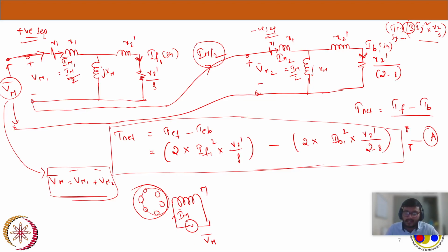Now let's compare this circuit and also the equivalent circuit. Now we have VM, okay, VM is okay. We have given the entire supply as VM, and then it should make the current flow as IM. But what is disturbing us here? The series current flowing through the stator is not IM, but if you see, it is IM by 2. So that's what is disturbing for us.